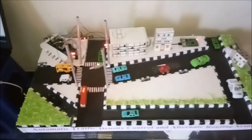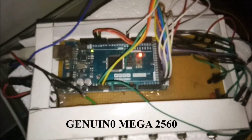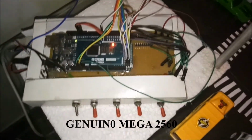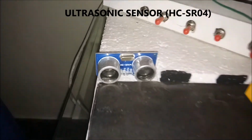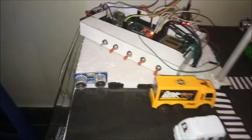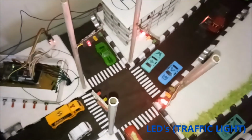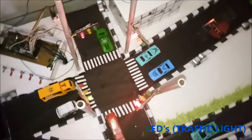The hardware used are Arduino Mega 2560, used to control the traffic working, which is designed for projects that require more input-output lines. It consists of 54 digital input-output pins and a 16 MHz crystal oscillator. HC-SR04 ultrasonic sensors are transducers that convert ultrasonic waves to electrical signals. They consist of 4 pins, and LEDs are placed in the signaling unit. Analog switches are used for changing the mode of operation of the signaling unit. LEDs are used as traffic lights here.